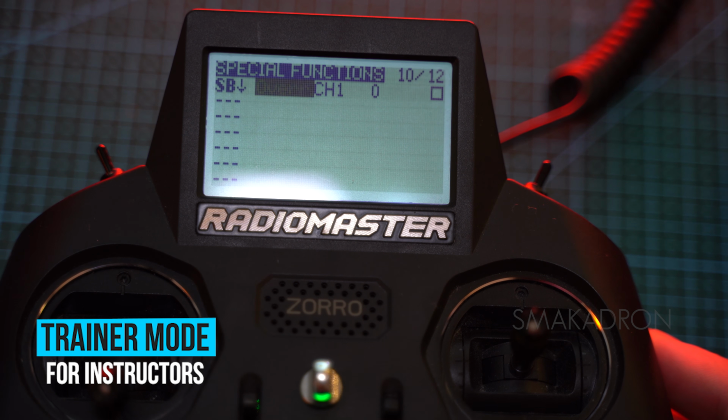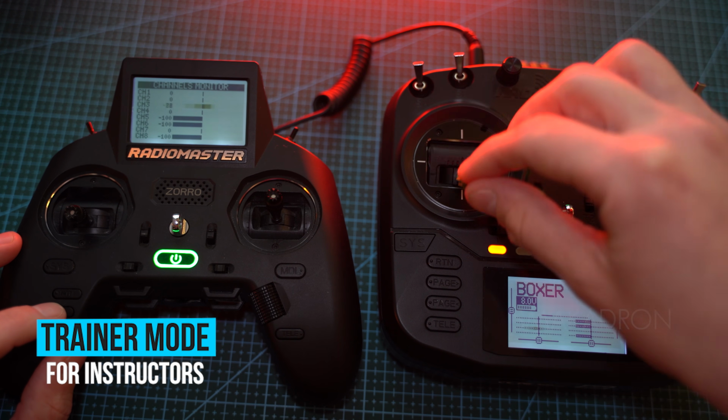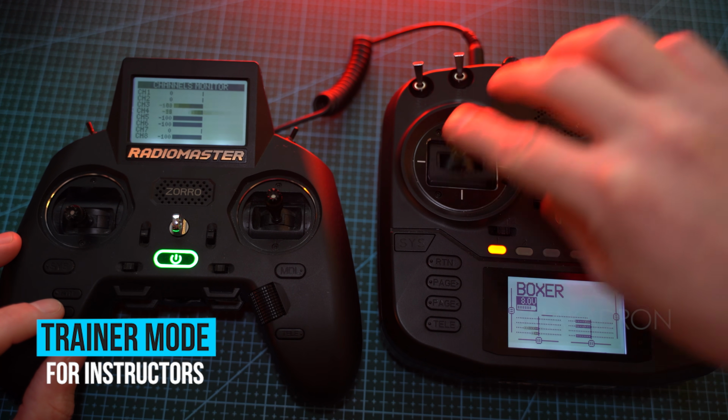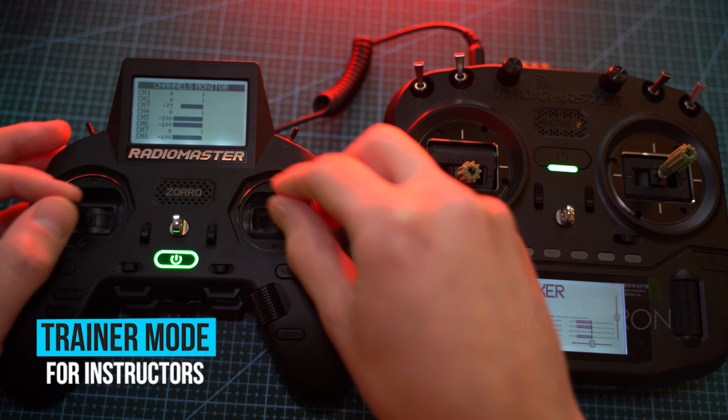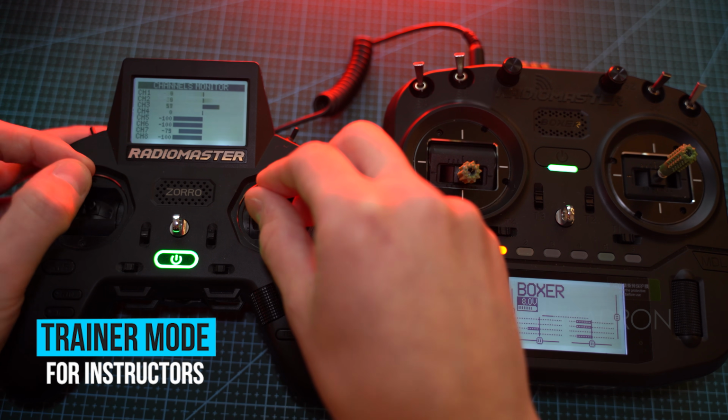Next, select Trainer from the list, then select Chans from the list. And at the end, check the box. That's it. Now we can check if everything is working. On the instructor's radio, set the selected switch to the down position. Go to the main screen. Press Page to go to the channel monitor screen, and we can see the students' inputs.